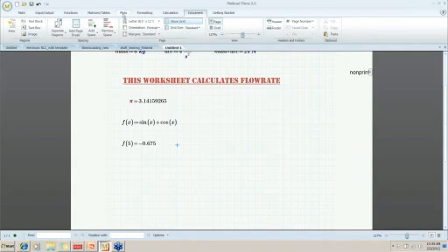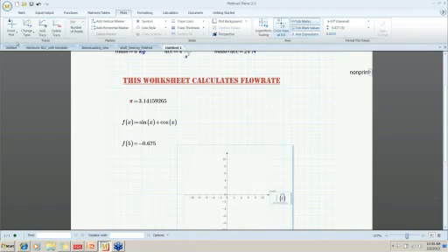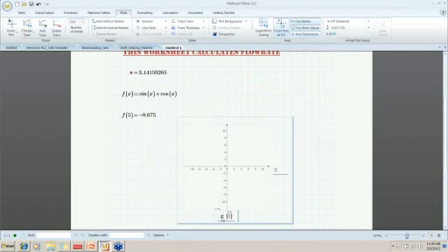Now we're going to click on Insert Plot. We're going to select XY Plot. And that puts in the framework for the plot for you. Okay, and so now what we do is here on the x-axis we put x, because that's the independent variable. On the y-axis we type f of x, because that's the y data. And then there's our plot.